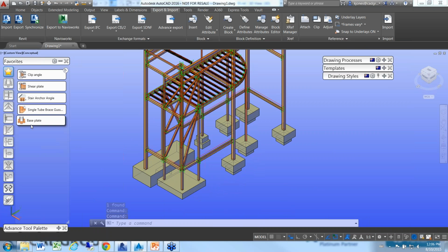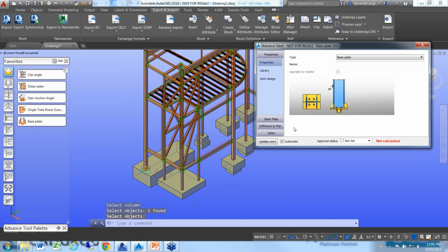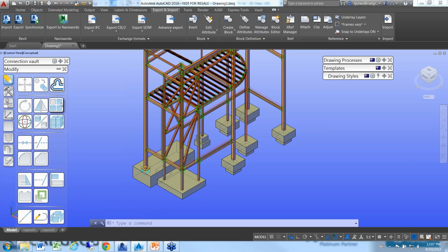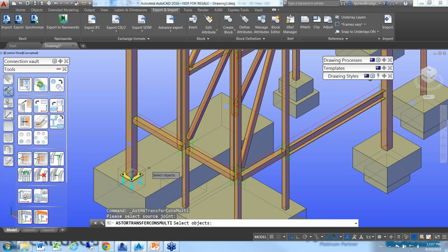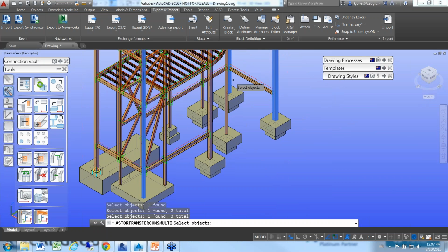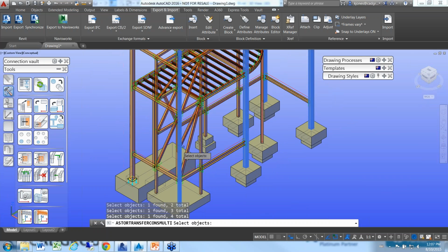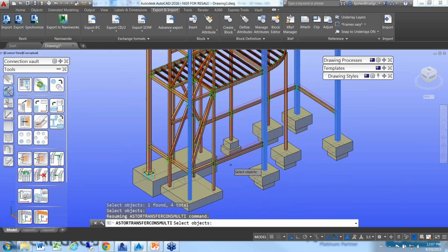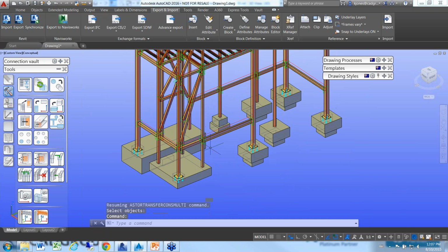So from simple connections, putting in things like base plates and elements such as that, we can copy those around and continue to work with some of those elements in there. Essentially, using some of the Advanced Steel tools, we can start to work on our construction side of things, more or less. So again, let's go in there and copy a few of the elements around that we're after. So some base plates on some of the elements. Straight away, I'm just using the Advanced Steel joints straight off the Revit members that have been imported in. Okay, so I'll throw a few of those down for now.